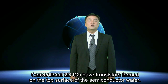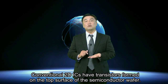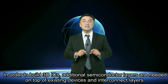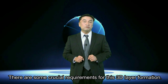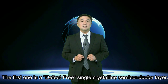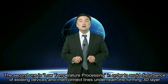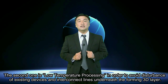Conventional 2D IC have transistors formed on the top surface of semiconductor wafer. In order to build 3D ICs, additional semiconductor layers are needed on the top of existing devices and interconnect layers. There are some crucial requirements for this 3D layer formation. The first one is defect-free single crystalline semiconductor layer. The second one is low temperature processing in order to avoid the disturbance of existing devices and interconnect lines underneath the forming 3D layer.